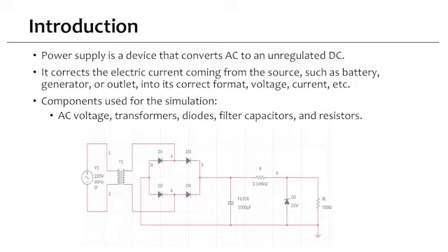So there are two diodes used here. The first one is the normal diode and the next is the Zener diode. A normal diode can only work if the circuit is forward biased. These diodes are used in clippers and clampers. On the contrary, Zener diodes are used in voltage regulators and they can work on both forward and reverse bias circuits.